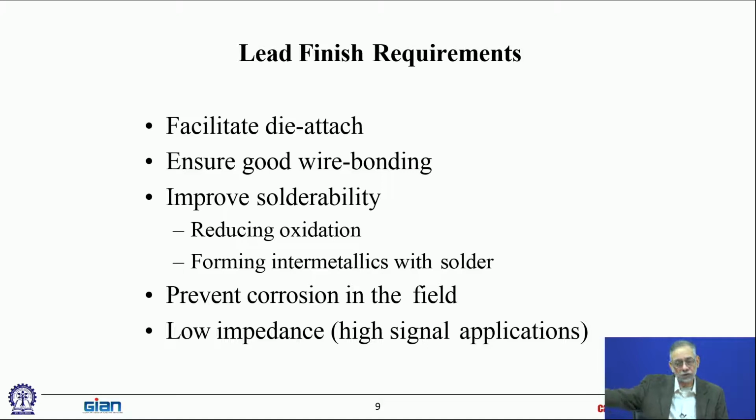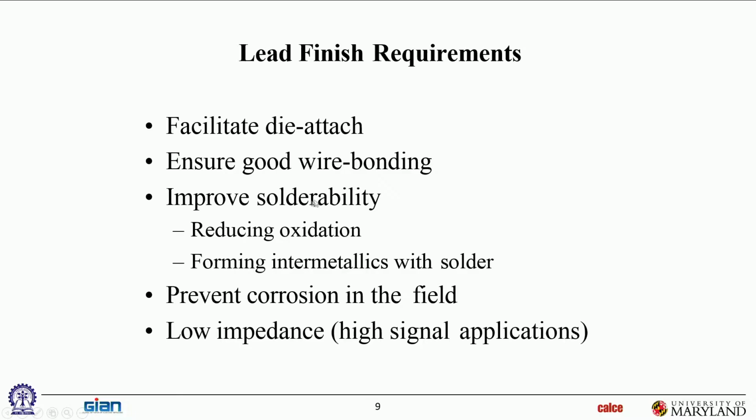Or even when it's trying to go through the reflow oven and you raise the temperatures up, they're going to instantaneously oxidize. Of course, there are fluxes used to reduce those oxides during the soldering process, but even then it's very hard to do soldering to copper that is already oxidized. So you want to preserve solderability, so typically some finish material is put on top of the copper to reduce the amount of oxidation. And we talked about what those finishes are in the last session on Saturday, where we talked about materials like immersion tin, immersion silver, gold over nickel, a variety of finishes, right?